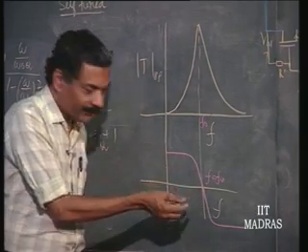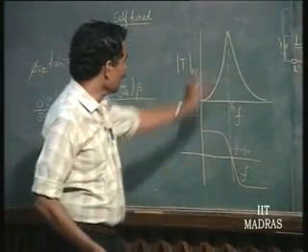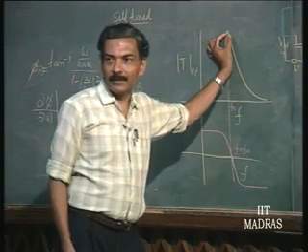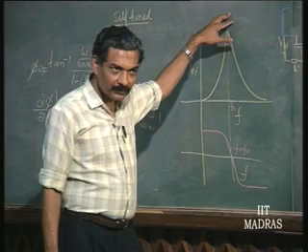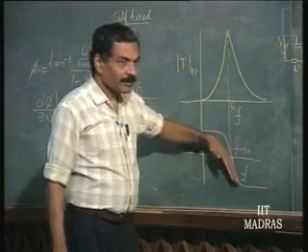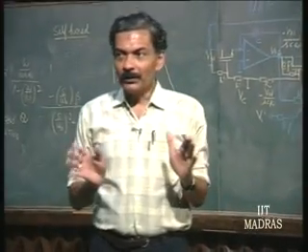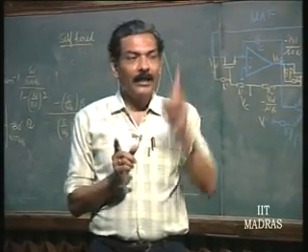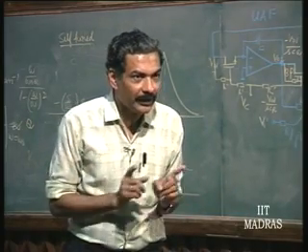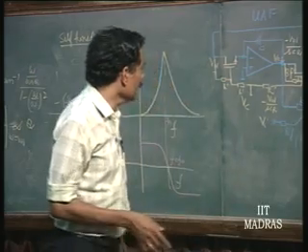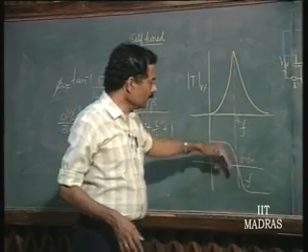find out the phase difference, because the phase is going to vary the maximum around that frequency, whereas the magnitude is not going to vary at all by definition, because it is flat, because it is the maximum, right. Phase variation is maximum. So, please remember that in any circuit, if you want to adjust the frequency exactly, you must always use the phase variation with respect to frequency, not the magnitude. So, phase detector is invariably used, not magnitude detector. So, that means I need a phase detector.